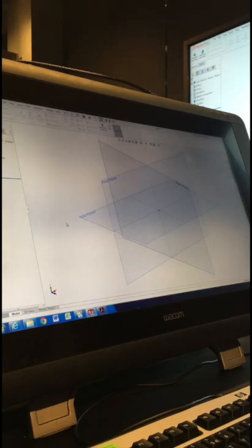If you don't reference the origin, then your part can never be fully defined. And you'll hear me talk about underdefined and fully defined a lot in these earlier weeks. That's to do with how you can control and set up your sketches so that they're really easy to edit, really easy to troubleshoot when you've got problems. That's also one of the main assessable criteria of the first project, that you've fully defined all your sketches. Okay, so that's some of the basics.